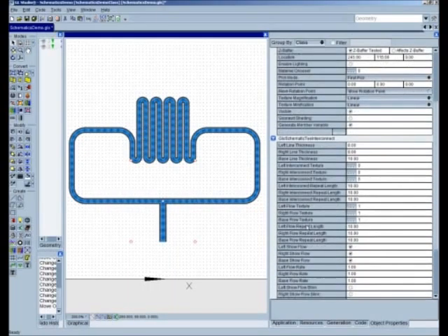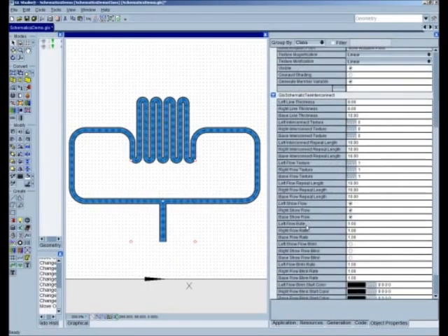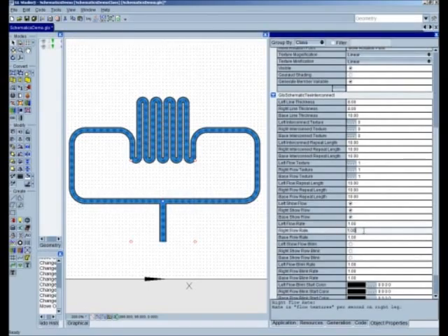To fix that, we're going to go ahead and change the flow rate for the right side. We notice right now it's a positive value. If we want to make it flow the opposite way, all we need to do is just set it as a negative value. And we see that setting the negative flow, it now flows in the correct direction.